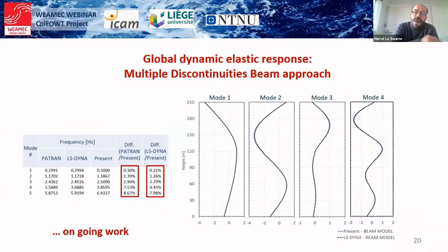And the first results show that the beam discontinuity approach allows us to rapidly and accurately calculate the modal characteristics of the structures. And here again, the discrepancy with finite element simulations for the natural frequencies and mode shapes does not exceed 8%.